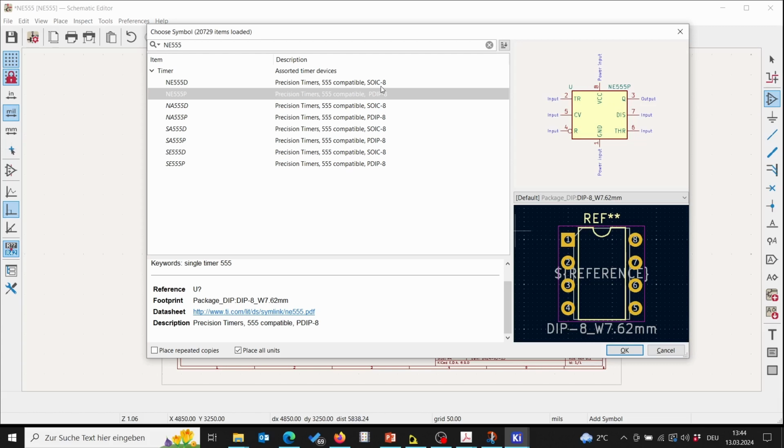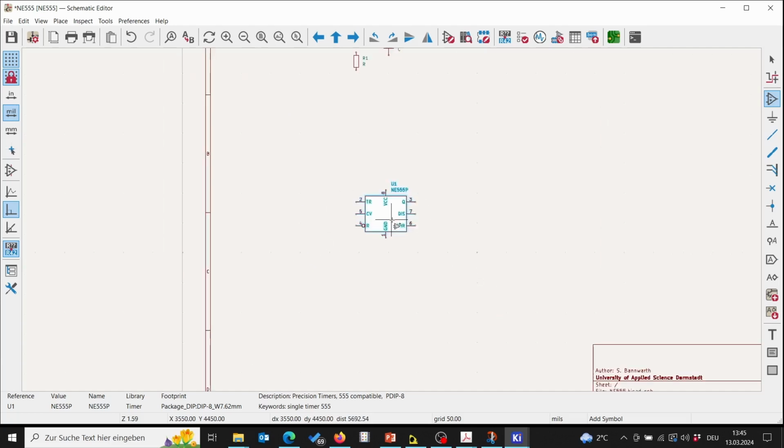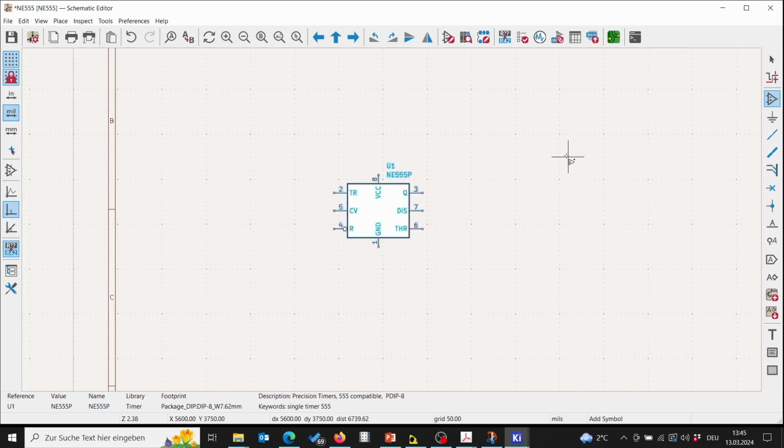We take the PDIP device and select it and place it in the middle. B1, C3, so B3, this is this area, so more or less in the middle. It's going to be here. Good. Then we zoom in a bit to place the resistors we need. So here we see that we need a resistor bridge with a capacitor.